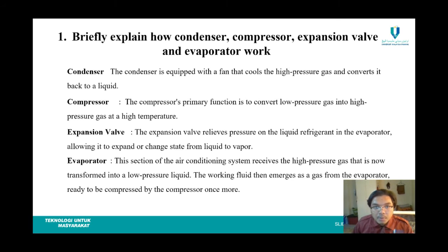Then the last is the evaporator. This section of the air conditioning system receives the low pressure liquid and the working fluid emerges as a gas from the evaporator, ready to be compressed by the compressor once more.